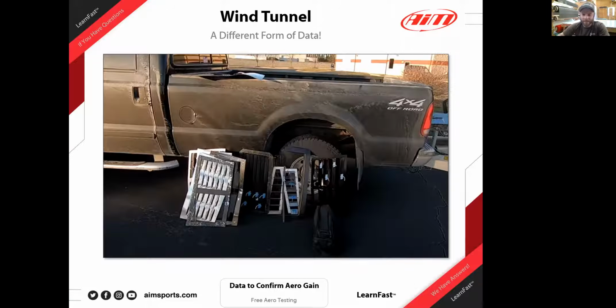But yeah, anytime we really went to the tunnel, we were doing overbody aerodynamics, like canards, louvers, wings. If you were to do a flat floor or a diffuser, you would want to take it with a grain of salt, because in a non-moving floor tunnel, you get a boundary layer that builds up across the floor as well as the car. So you will actually get a little more pressure under the car because you have two boundary layers building up. Whereas with a rolling floor, you don't get the boundary layer along the ground. You get just the air moving across the car. I hope that all makes sense. So if you were doing underfloor aerodynamics, you could still get good data for sure, but you would want to take that into consideration a little bit.